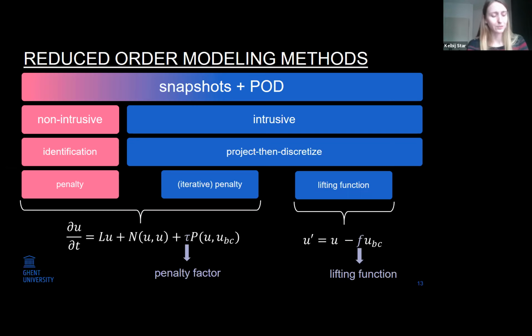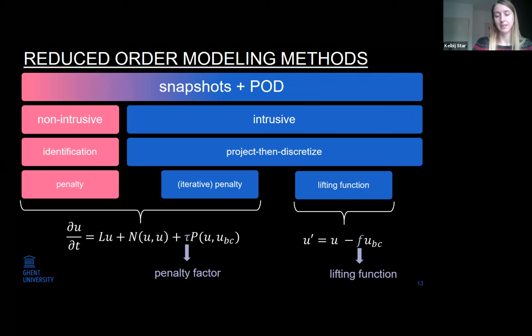The only thing to take into account with turbulence is that we're truncating, so I'm only including the first number of POD modes. If you look at the energy cascade, all the dissipation is more or less contained in the smaller, higher POD modes. They have less energy, but therefore they're in the smaller scales.